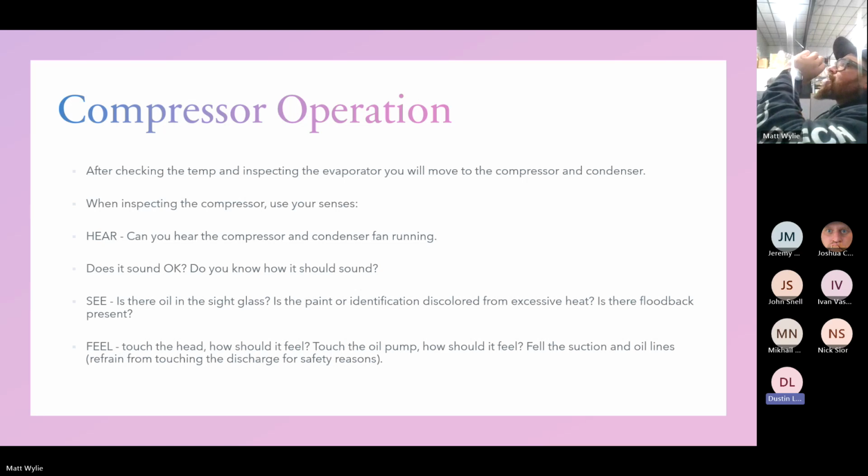Once you start picking up different voltage readings through top and bottom of the same line, just like a pressure switch, if my pressure switch is open, I've got voltage. If you're seeing spikes and your voltage is popping in and out and you're getting weird readings, top of 1 to bottom of 1 or top of 2 to bottom of 2, there's a good chance your contacts are pitted and are not making a good solid connection.